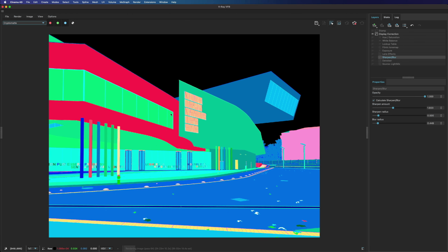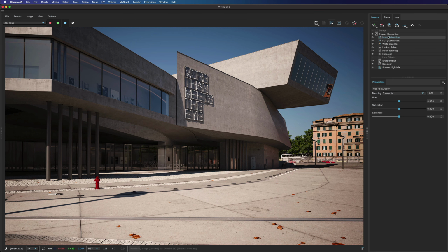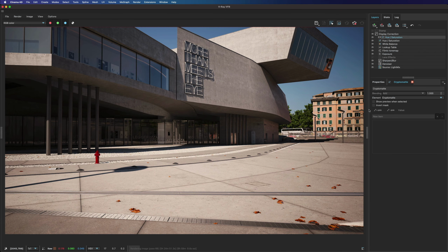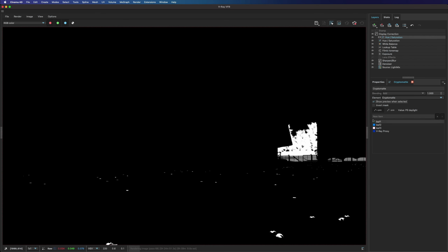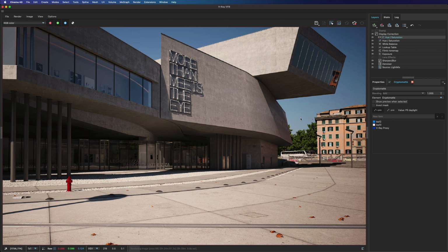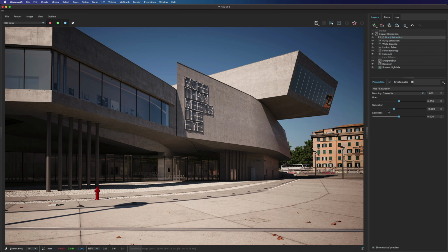We have the render elements over here, and all objects have different color IDs. To use it is extremely simple. Choose, for example, a hue saturation layer, then add a Cryptomatte mask. Choose the picker and click the elements you want to modify. Here you can also see them through a mask preview. If needed, you can also remove these elements through the picker or minus button. Once we selected everything, click on Properties, and now you can lower the saturation.